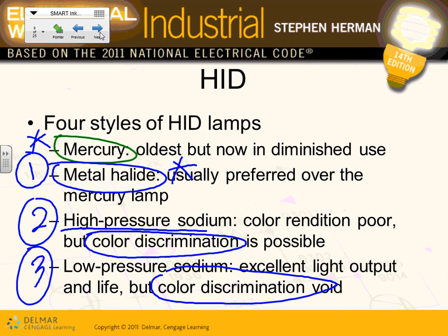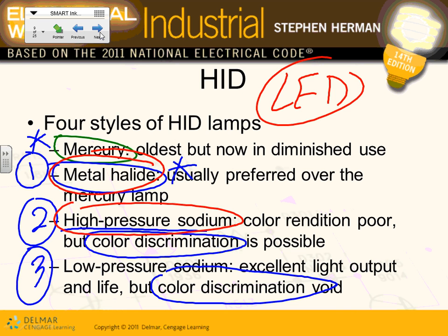Any comments, guys, about these options? Unless you use LEDs, your options are really limited to metal halide or treated high pressure sodium for outside lights. We used LEDs, remember? For years, Joe, when we did the projects, we used metal halide and high pressure sodium outside. This year and last year were the first 2 years we used LEDs in the industrial project. Our option was always metal halide, high pressure sodium. Okay, so that's your option.